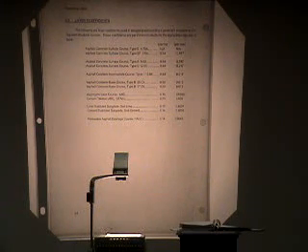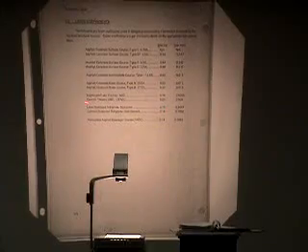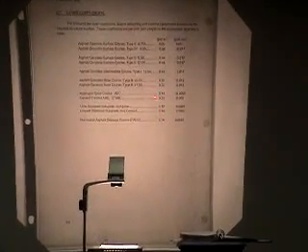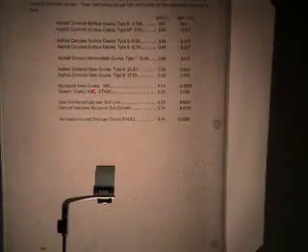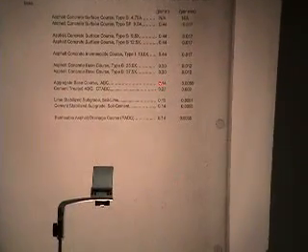If you look at it in reverse, asphalt base is about twice as strong as aggregate base per inch of depth. And then when you treat that aggregate with lime, it becomes 0.13. If you treat that ABC with cement, it bumps it up from 0.14 to 0.23 and so on.